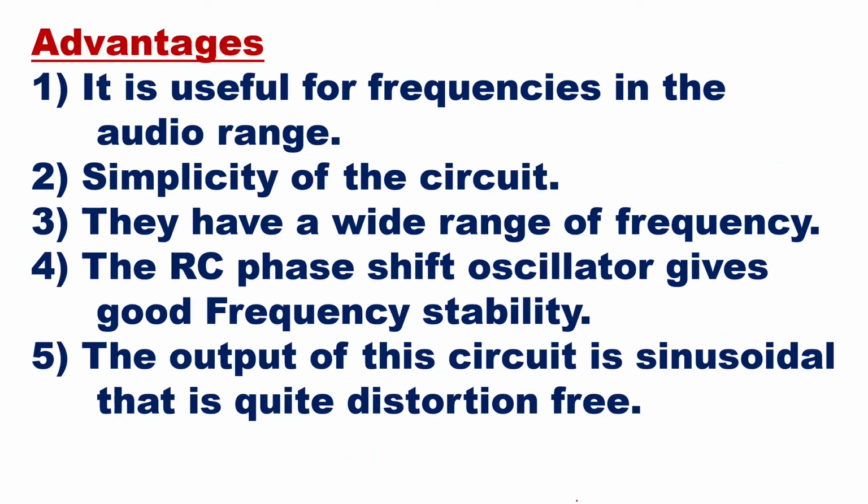Then what are the advantages of the RC phase shift oscillator? It is useful for frequencies in the audio range. There is simplicity of the circuit. They have a wide range of frequency. The RC phase shift oscillator gives good frequency stability. The output of the circuit is sinusoidal, that is quite distortion free.